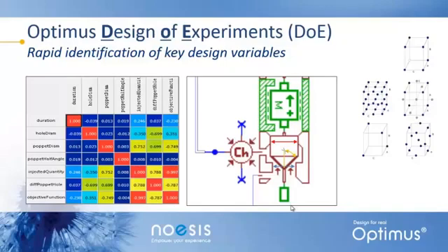least expensive design. It can also help you to reduce the complexity of your simulation, which of course will be very important for CFD, where eliminating any design variable can help speed up your runs. So this sensitivity and ranking of the different input variables is exceedingly valuable, especially if you have a large number of parameters and you don't know where to start.